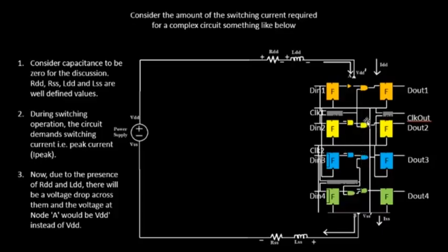Also, whenever any piece of the circuit is switching from logic 1 to logic 0, it is the responsibility of the VSS to take that amount of charge. So when we say logic 1 to logic 0, the capacitances present in this circuitry get discharged, and those discharge currents should be handled very well by this power supply ground line. Okay, so that's the intent.